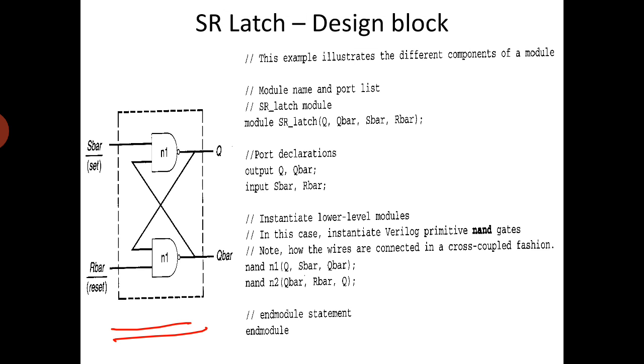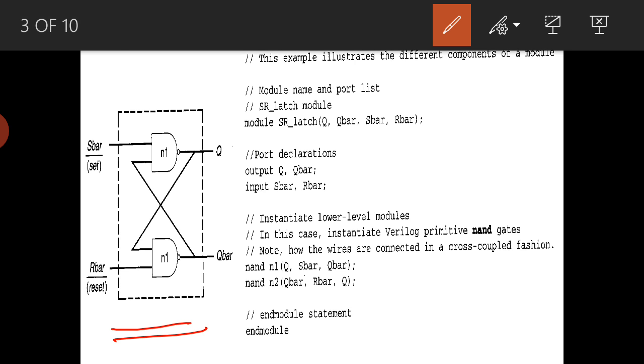So what is a latch? A latch is one which stores a value. For example, a 1-bit latch will store a 1-bit binary value, which can be either 0 or 1. This is the SR latch, the logic circuit or logic diagram of the SR latch.